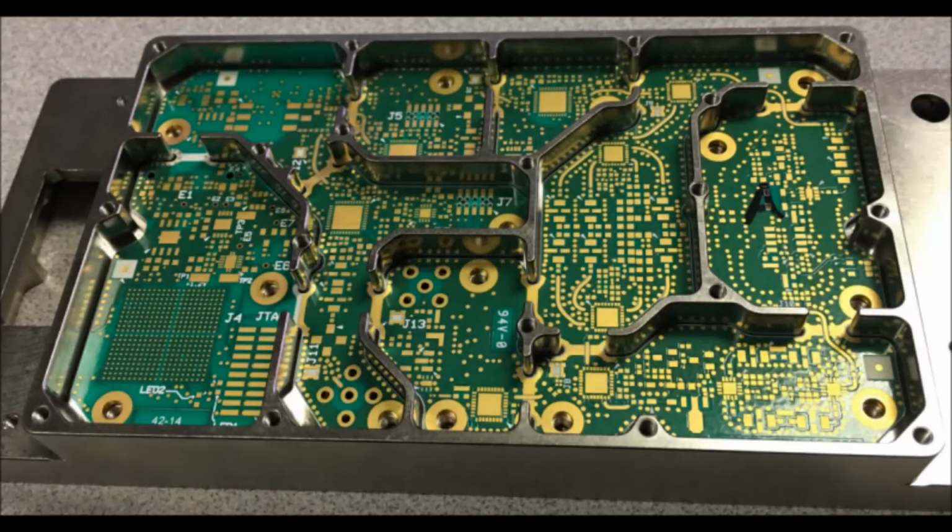the board to be used in an RF chassis with shield walls that either protrude through slots or cutouts in the PCB or that sit on the surface of the PCB. Here's an example of an RF board and the metal chassis that it's mounted in. There are cavities milled down into the metal. The cavities and walls between them help to isolate the different RF signals from each other and from the rest of the system outside the chassis.